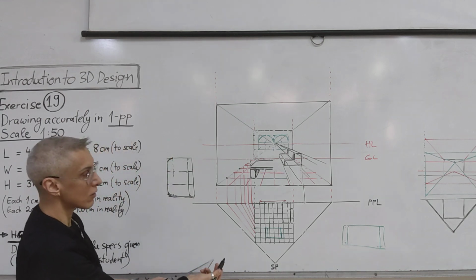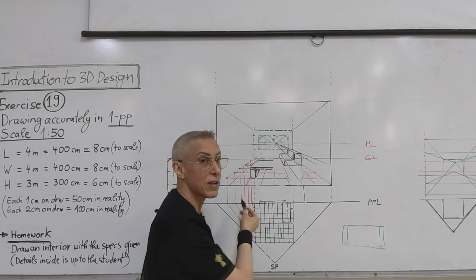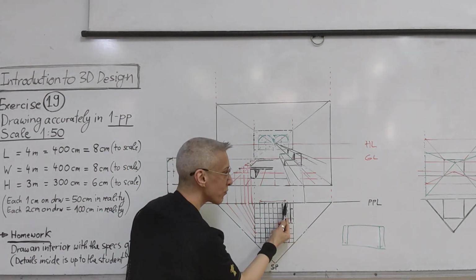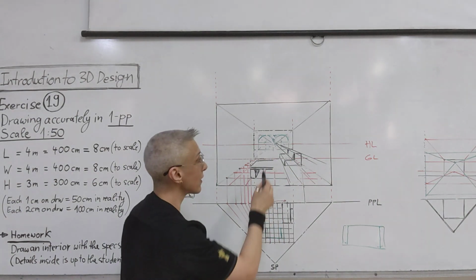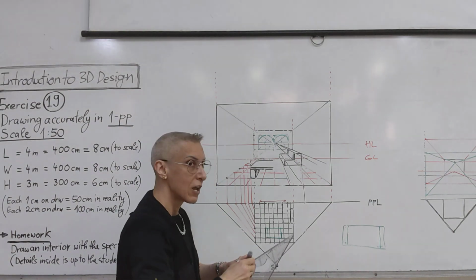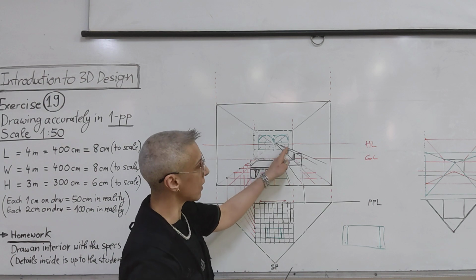So after that, any point you need from the station point, you see where it will intersect the picture plane line, like in that previous example. And then from these points you take up and see where it will intersect the corresponding lines. From the back you measure the heights, okay? You decide the heights of the object. And you can draw it here.